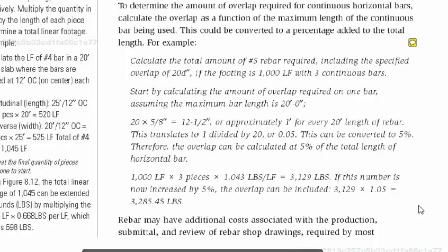Also, when you're working with the reinforcing bar, there is a wastage. Sometimes you cut a bar, or you have to cut bars. So you have to account for both of those to get the right length. Generally, you'll find designers try to use whole bars or segments that minimize the amount of wastage. But remember to do that and include that in your total amount of pounds or tons, whatever it comes out to be.